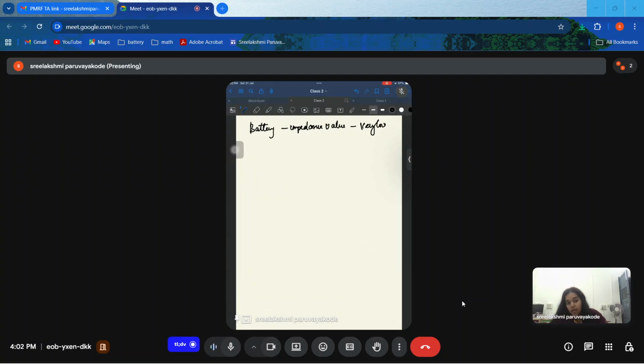Now let me give you an example where I'm applying a DC potential of 10 millivolt. Let me take the case where I'm going to run the battery in pseudo potentiostatic mode, giving a DC potential of 10 millivolt. We already know that the impedance value for a battery is going to be very small. For example, let me say the impedance value is 0.001 ohm.